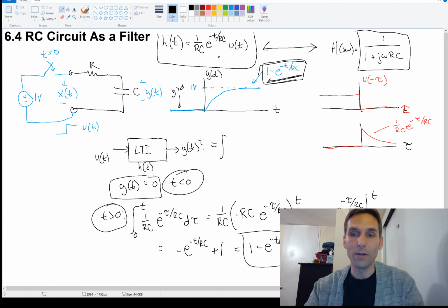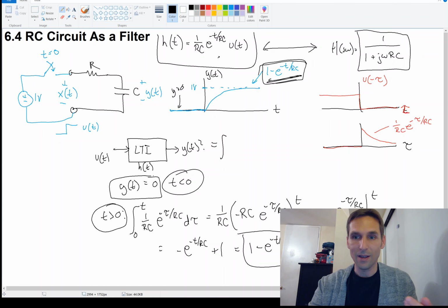So now, I do have a little bit more that I want to say about this RC circuit. And in the next video, we're going to code it up in software. So, you know, if you actually had a resistor and you actually had a capacitor, you can make an analog circuit, and this would be a continuous time system like we have here. But I don't want to say simulate, but we can maybe discretize, meaning we convert to discrete. We can discretize this system into a computer program that does the same thing, i.e. a low-pass filter, but for discrete time. So that's the next video, and I'll see you then.